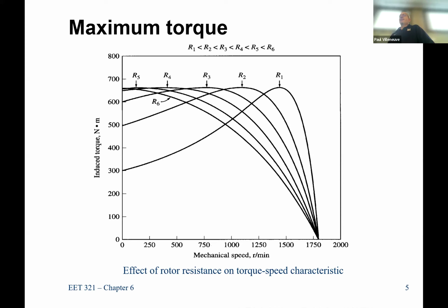Nobody here's a lead foot. When your car's got a lot of torque, when you have your max power at no speed, you take off and you get up to speed really quickly, as opposed to having to wait till your engine gets to 4,000 or 5,000 RPM, whatever it is, to get all that torque. Wouldn't you want it to be perfectly flat until you were reaching your threshold? So more torque means the load starts faster. It's got up to speed at a faster rate. So it ideally would be this if we could.